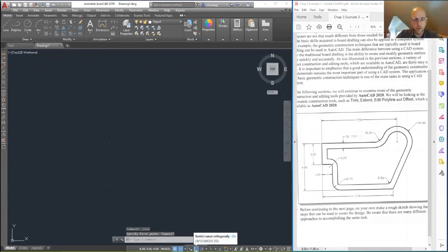All right, I've got ortho mode turned on. It looks like a perpendicular symbol. This just means it's going to restrict my cursor movement to horizontal and vertical lines. So if I'm drawing a vertical line, all I have to worry about is the length. I don't have to worry about the 90-degree angle, that's fixed no matter where I have my mouse. Or if I'm in Cartesian coordinates, I don't have to worry about the X value. Let's type in the vertical value, the Y coordinate.